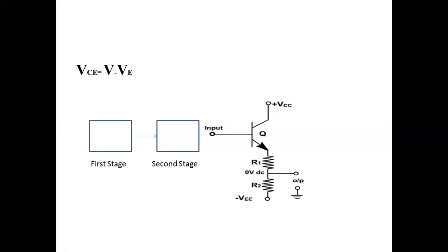In the saturation region, as its name suggests, even though you are giving the input, the output is not going to change. We are using this transistor as an amplifier. That means we expect that though I am giving a small input, I get an amplified, larger output. But if your transistor is moving towards the saturation region, you are not able to work the transistor as an amplifier. It will be stuck and saturated. Though you are providing the input, it is not going to be amplified and you are not getting it at the output side. That happens whenever the transistor is moving towards the saturation region.